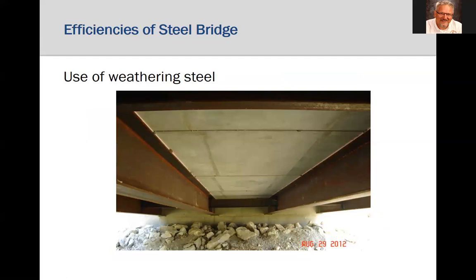Finally, one of the costs for steel bridges is corrosion protection, since regular steel rusts. However, weathering steel, when applicable, is a low-cost protection system and requires little maintenance for long-term corrosion protection. If weathering steel is not applicable, galvanizing, metallizing, painting, or the use of stainless steel may be a cost-effective method for corrosion control. And we'll talk about these durability and protection systems in lecture 4.